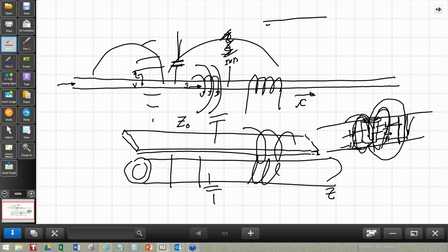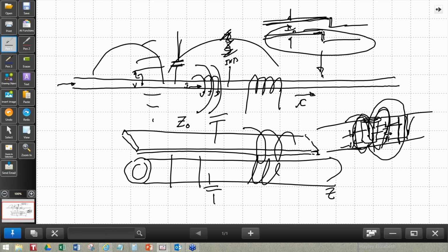If I have a differential trace, and it goes through a via here, and I have the other side, a trace that's part of a differential pair, and I have another via there, and these go down at the same place, and the spacing of this is approximately equal, some fraction of a wavelength, then because they're supposed to be somewhat coupled, that's going to be okay. But if they're different signals, then you probably want to take one of them and move it much further away. How far away? Well, it depends on a whole bunch of other shielding factors, but it's generally large in comparison to a quarter wavelength is ideal.